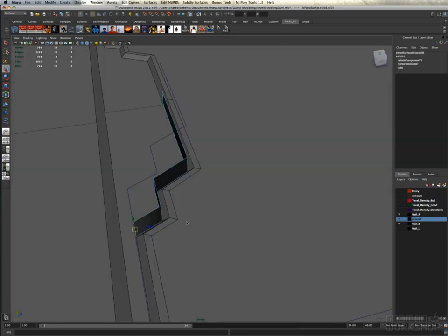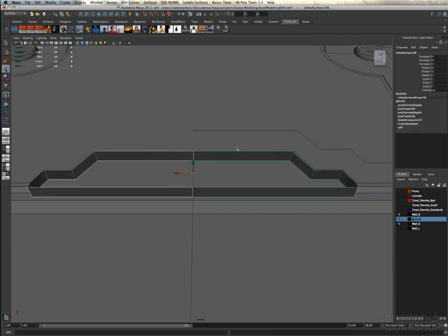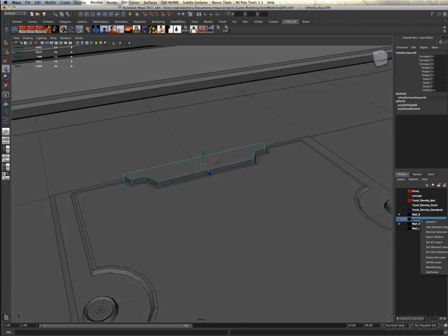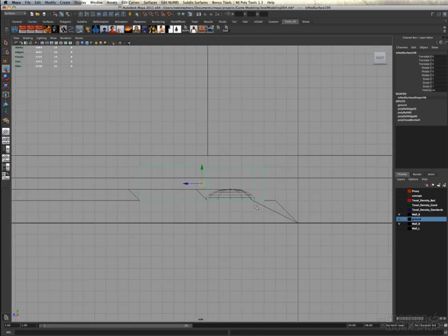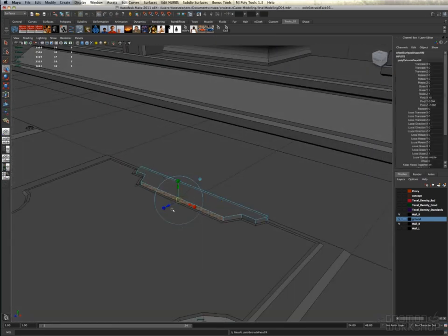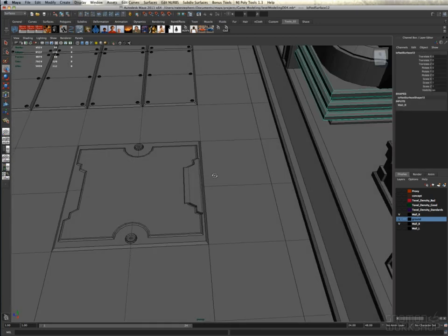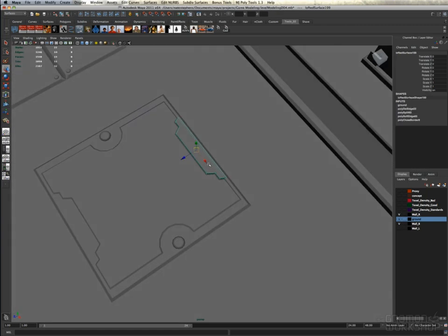And now here I've gone back to my original curves and pulled out a shape that will kind of nestle inside of the larger shape here. So never delete the curves that you're using to build until you're sure you won't use them again, because here they were useful. I was able to repurpose them for another piece, and it'll fit perfectly inside my larger panel here.